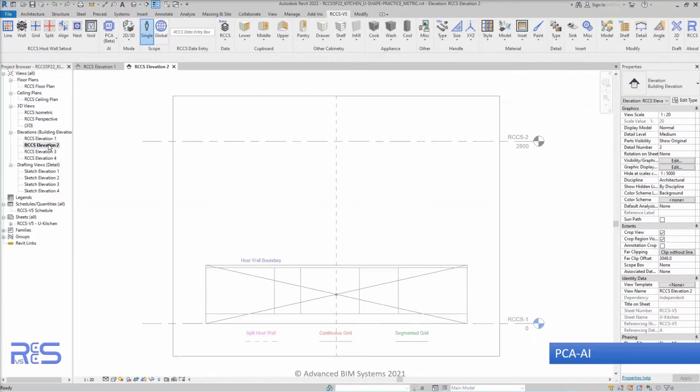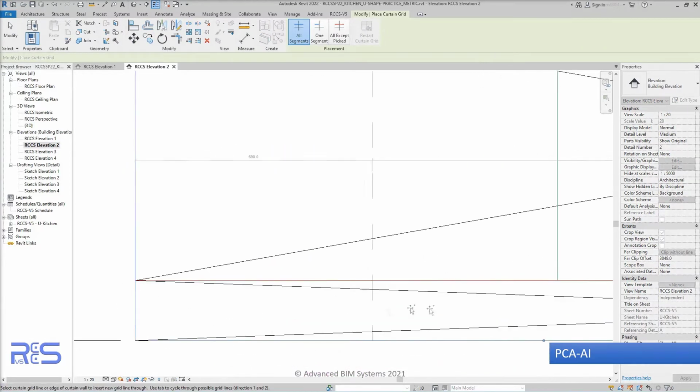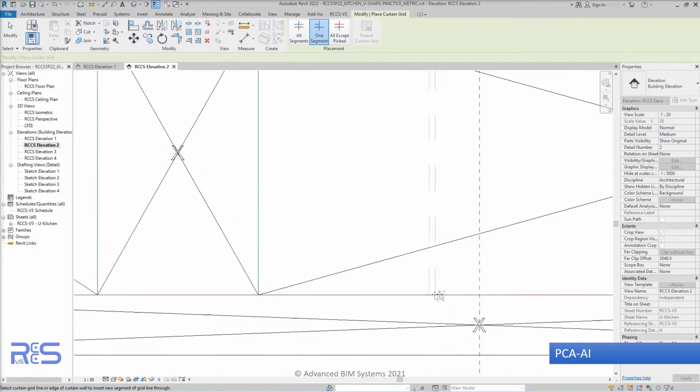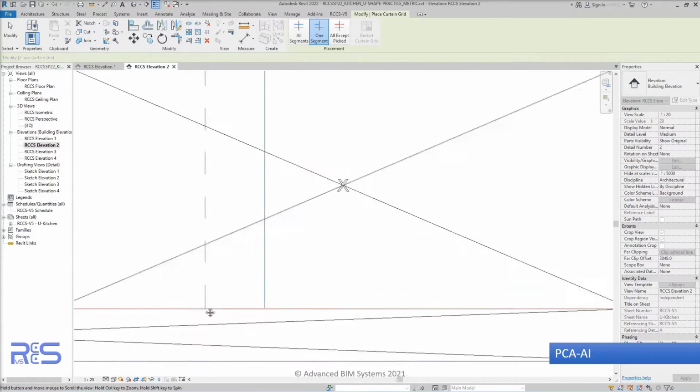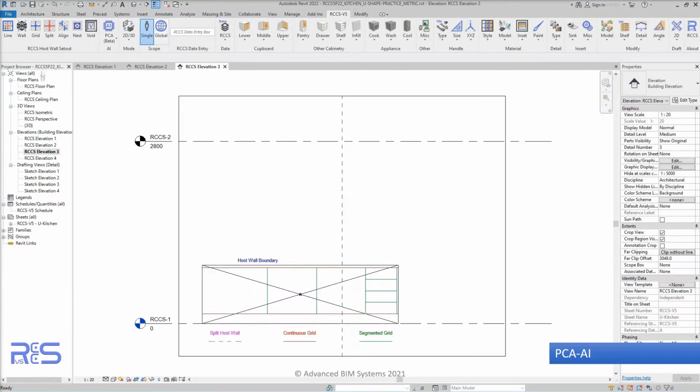In the event that you've made a mistake, either use undo, back up, and redo it again, or perhaps go through and remove those splits by using the Tab key on your keyboard to select the splits to be able to delete them. Then you can go back and split them again.